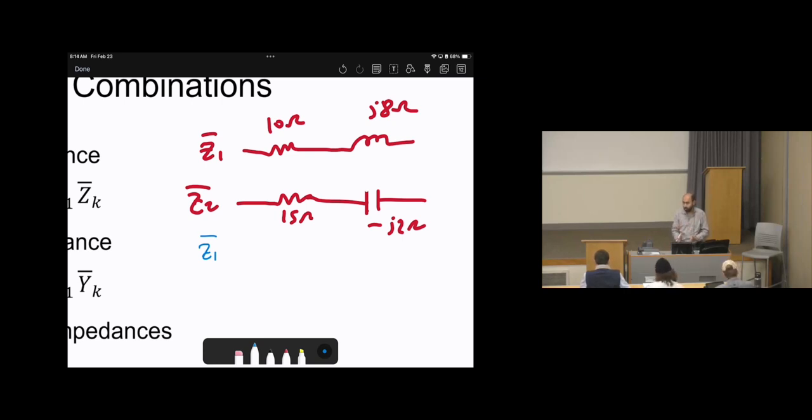Okay, how? If they are all in ohms, they are all impedances. So I'm no longer saying this inductor, this capacitor; this impedance and this impedance are in series. So their series will be their sum. It's going to be 10 plus J8. J8 and 10, you cannot add them together because it's a complex number, and this is a representation in rectangular coordinates. So we can keep it like this. You don't even need to use the calculator. It's 10 plus J8. That's it. We know the rectangular coordinates and the polar coordinates. Most likely, for the impedance, keep it in rectangular coordinates like this. You don't need to convert this to polar.